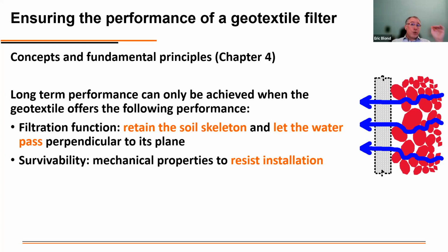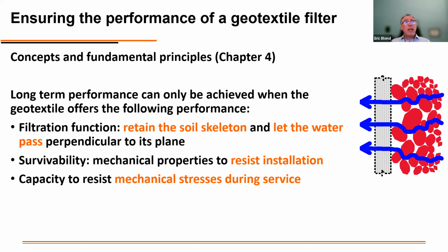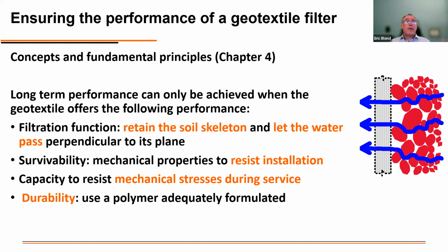Another aspect which must be achieved is survivability. It must present sufficient mechanical properties to resist installation. It must also resist mechanical stress which is going to be suffered during the service life. And finally, we must use a polymer which is adequately formulated and which is going to last long enough. For example, I've seen situations where polyester geotextiles were used in mining environments.